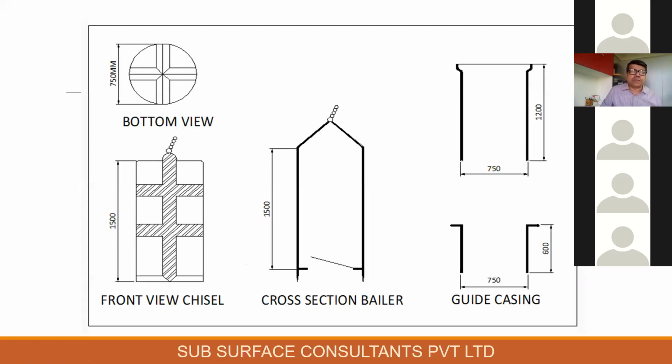If the chisel fully goes inside the rock and a small gravel falls inside the hole, it will jam between the hole diameter and this blade here. If it gets stuck here, then the chisel can get stuck inside, and sometimes even the wire rope will break and nothing will come out. Therefore, to ensure that such a thing doesn't happen, hard facing is done at this area and this area, so that by friction the gravel can be crushed. Okay, let me go to the next slide now.